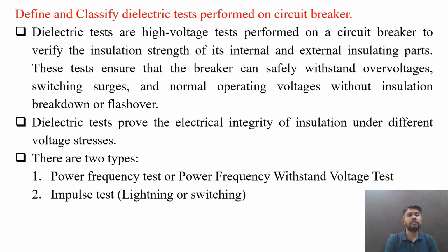There are two types of dielectric tests performed on circuit breaker. First is the power frequency test, or power frequency withstand voltage test. Second is the impulse test, or say lightning or switching surges test. So these are two dielectric tests performed on circuit breaker to verify its insulation strength.